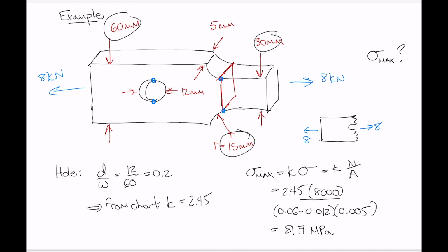Stress concentrations are super important when you're dealing with brittle materials, because in a brittle material, when the ultimate stress is exceeded, that results in a crack forming, and cracks in brittle materials propagate very easily and rapidly through the material.